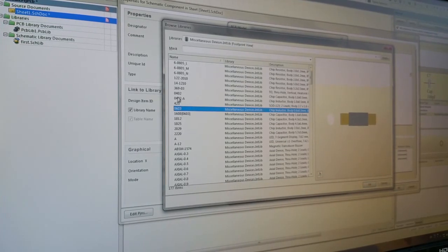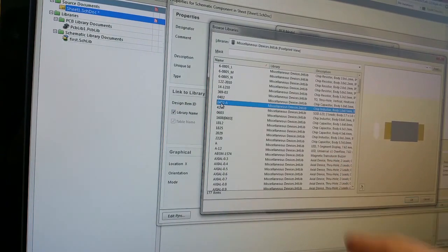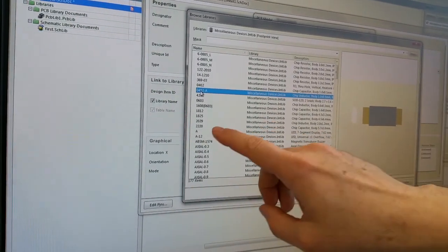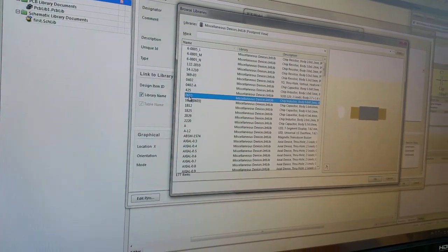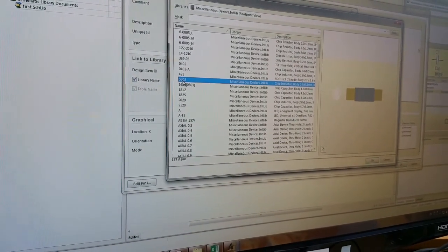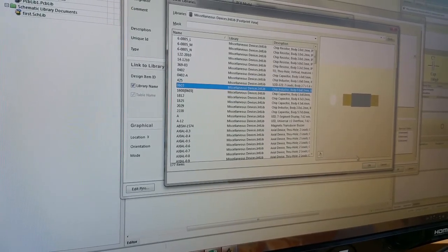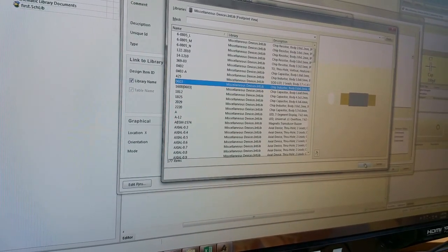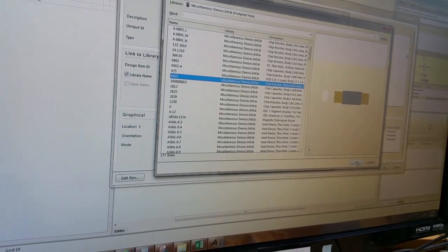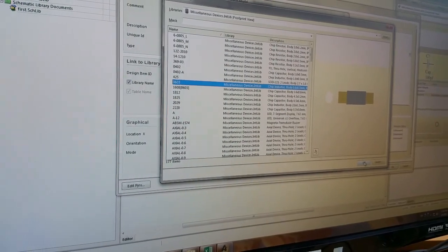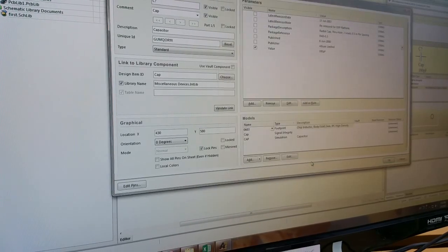These are capacitors, I think. No, you can use it for everything. This is just surface mount. This is the standard size for the surface mount. We can put whatever we like. You can link it with the capacitor, link it with the resistors. It's up to you. Okay, let's link that one. But what about the name? The name will be resistor, because you click on the resistor. The names come from the schematic, not from here. So we link that one now.